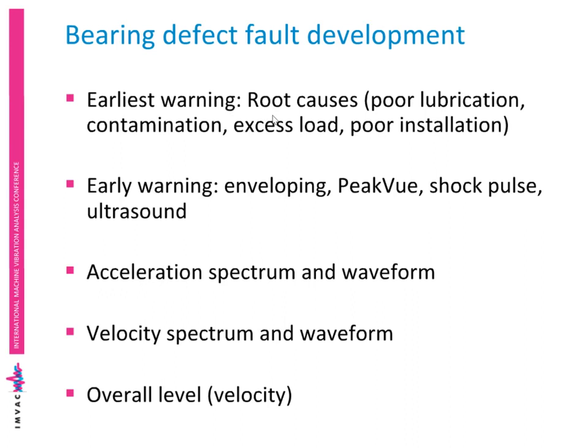It's really important to understand the root causes, like poor lubrication, contamination of the lubricant, excess load from unbalance or misalignment, resonance, and so on, and poor installation practices, the bearing being damaged when it's installed, cocked on the shaft, and so on. But this will give us the earliest warning.